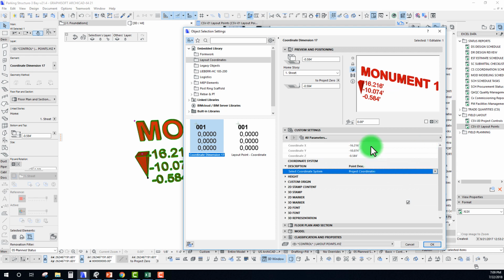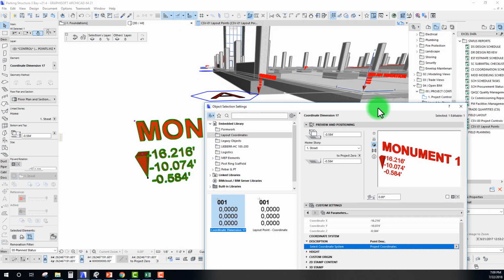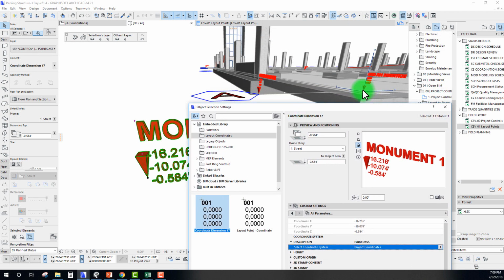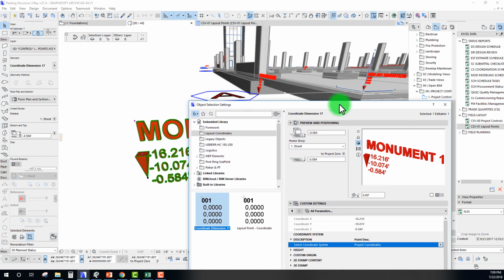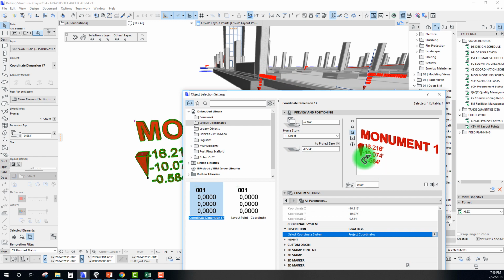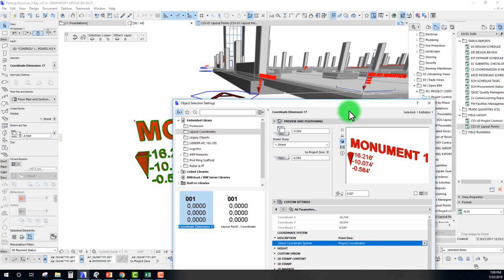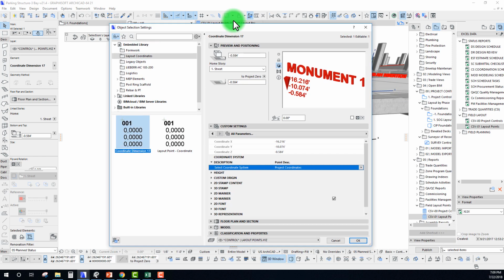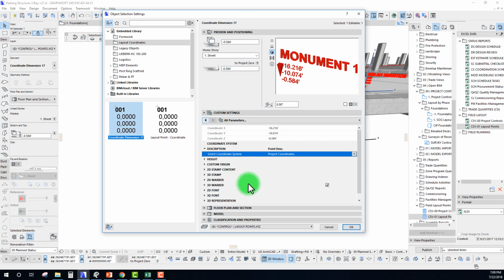So with our project coordinates, it's a little bit more dummy proof in my experience, and it really gives you a nice visual feedback, just knowing if your 0 point is, say, your southwest corner every single project, then if you have a positive X, positive Y, positive Z, it's really easy to understand where those points are coming from.